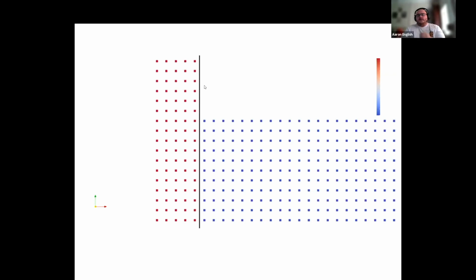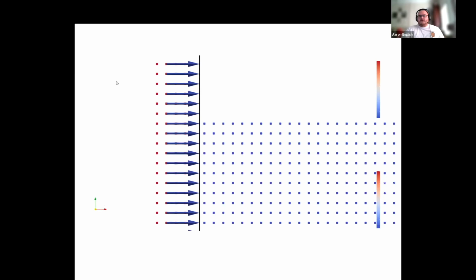What you want to do is define your geometry, so this black line here is your interface or your physical boundary. And yes, you need more than one layer of boundary particles. What you want is enough boundary particles so your kernel support for a fluid particle near the boundary is complete. In this case, I think there are going to be four layers that are then going to generate the normals to get the ghost nodes. I hope that helps, Mashi.